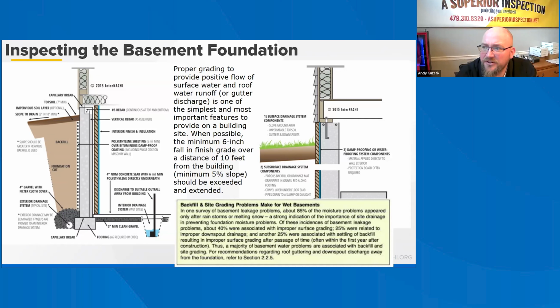A drainage layer underneath the entire basement floor slab, coupled with weeps to a drainage system around the foundation perimeter, may be more effective in eradicating conditions where potential for high groundwater levels near the basement floor elevation exists. Experience has shown that diverting moisture with a drainage system before it enters the living space is more effective than trying to seal moisture out of the foundation.